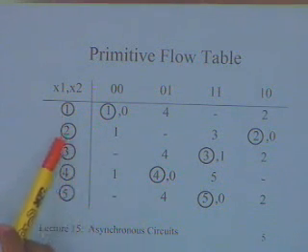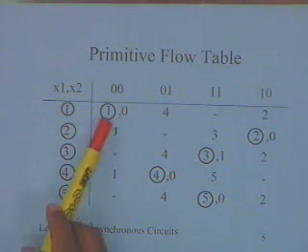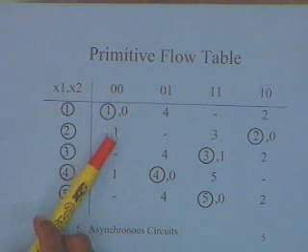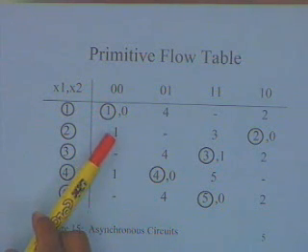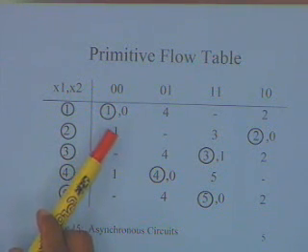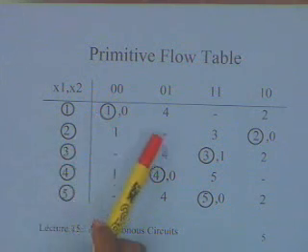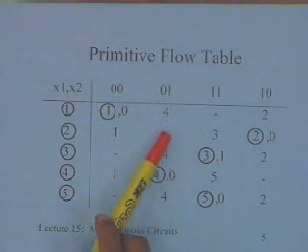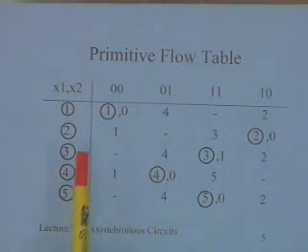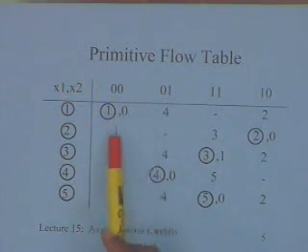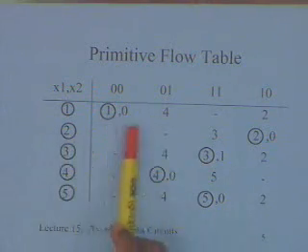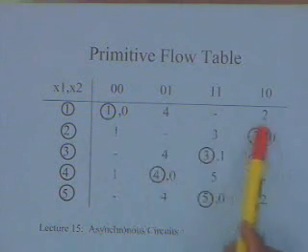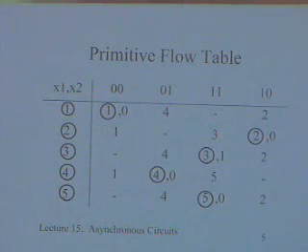If I consider 1 and 2, they are compatible because in this column there is a transient state and there is a stable state, so I will not consider them to be different as long as I have marked them to be the same. So this transient state 1, right now I don't care here, so these are compatible, this is compatible, this is compatible. Column-wise, if every entry is compatible for all the columns, referring essentially to all the input states, then those two rows are compatible.